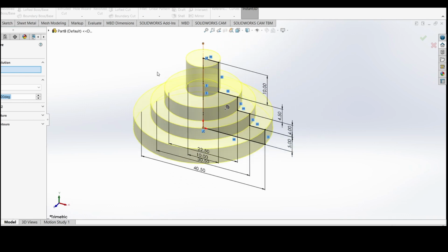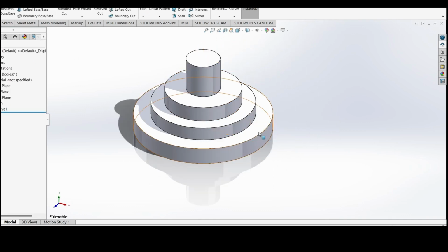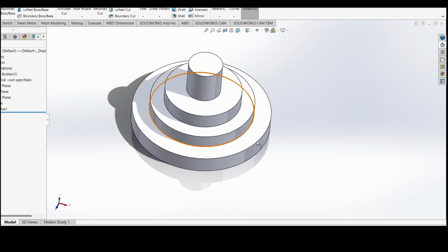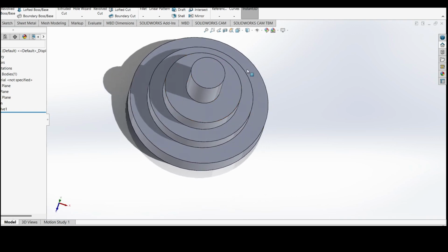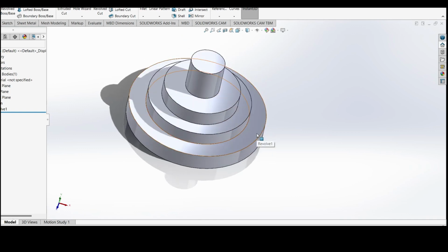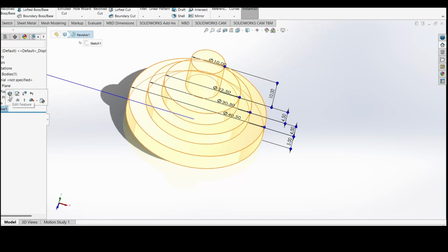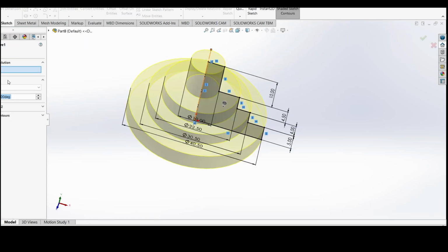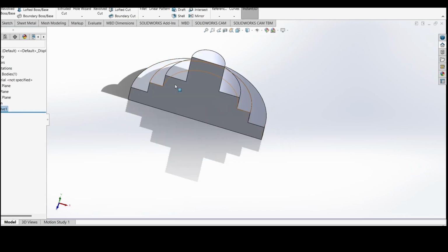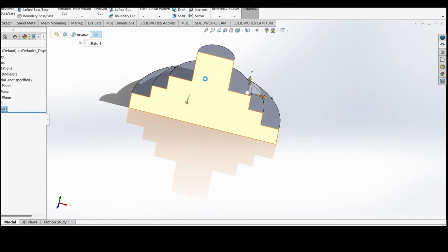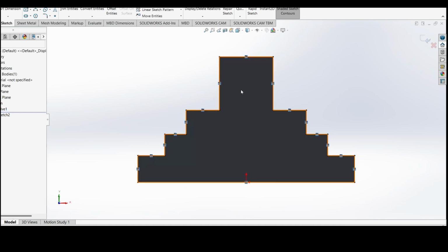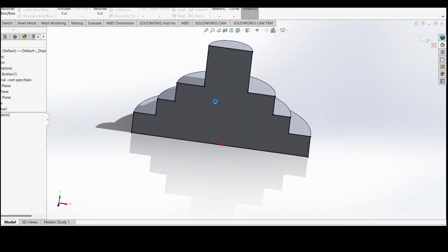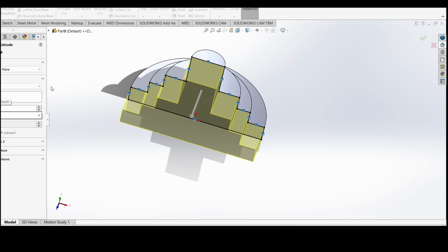We can do our revolve. Excellent. But we noticed the feature, it wasn't just a circular revolve, it kind of came out flat, right? Oh, wait a second. Maybe it's better to do this as a 180-degree revolve, because now I can use this plane to make a new sketch with converted entities that I can then extrude. Okay, it looks like 15.